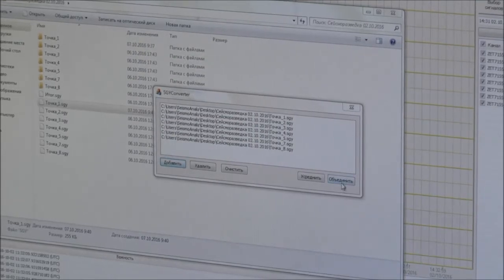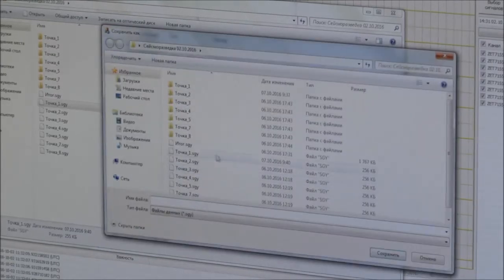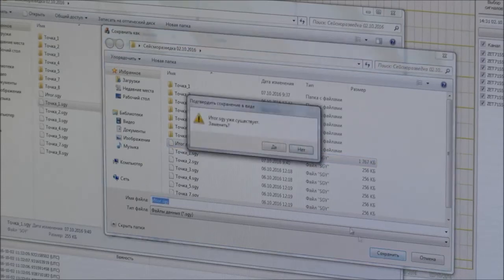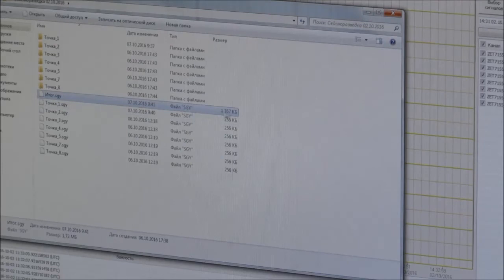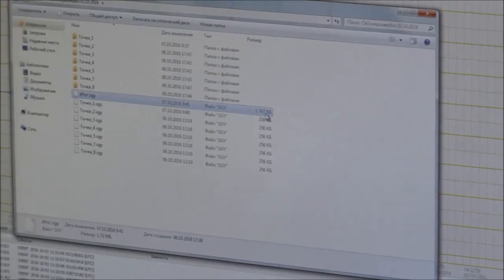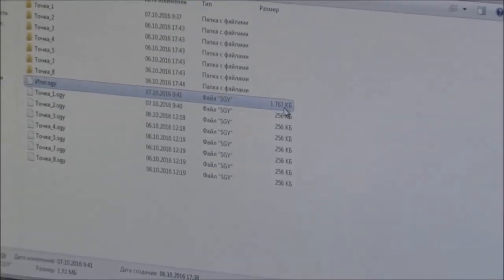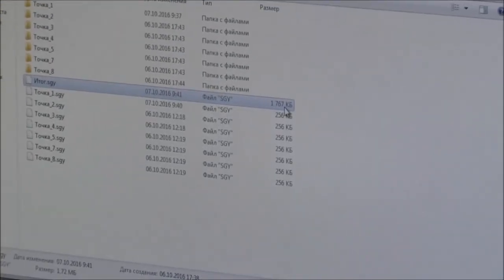Now we select Merge option. It will be activated for all files. The resulting file will be called Final File. Select Save option. We have updated the file. Now it contains a set of inputs for each of the short points and for each of 8 digital geophones.